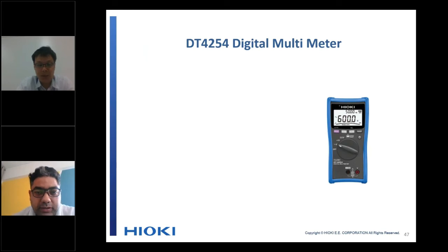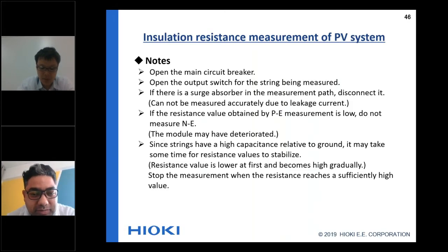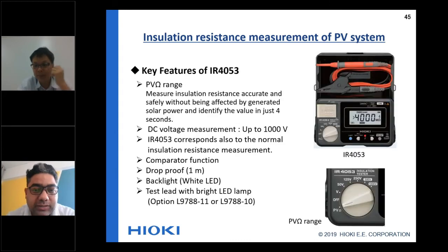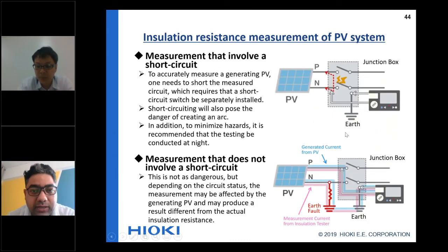So finally, Sagata-san, sumimasen. Related to that insulation tester, it's a normal insulation tester, but we have developed this product as per customer demand. They were facing some kind of issues while doing insulation measurement, especially when there is rain at the solar power plant. So what is happening when it is raining? Nothing, no kind of fault is there, but the leakage current increases at that time because the soil is wet.